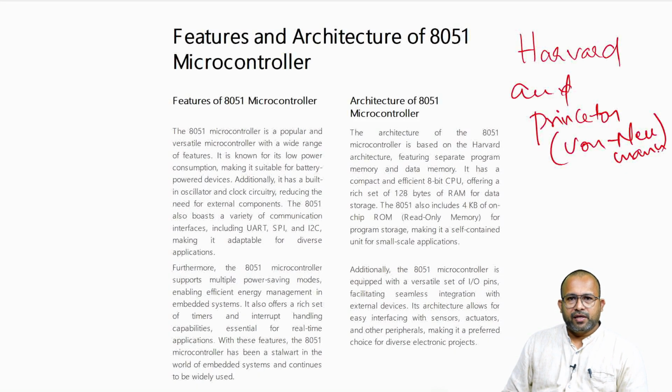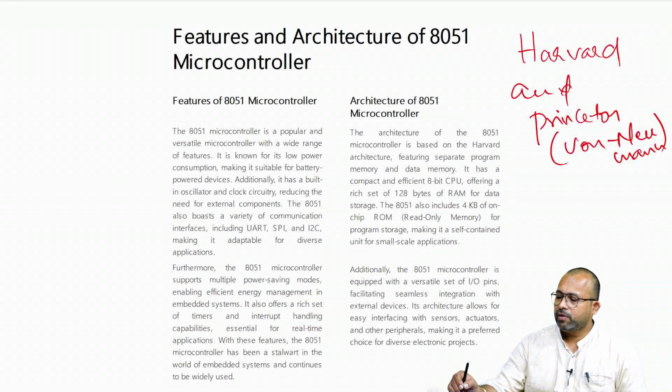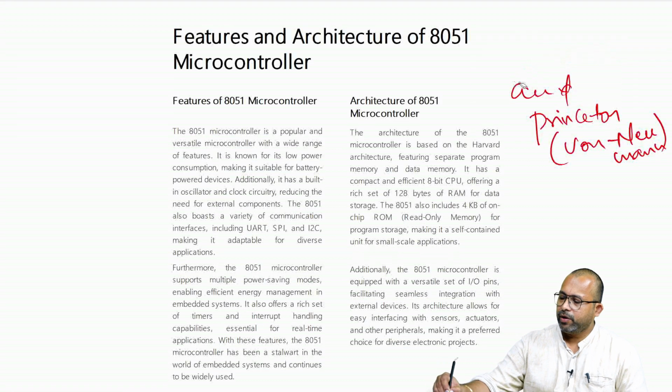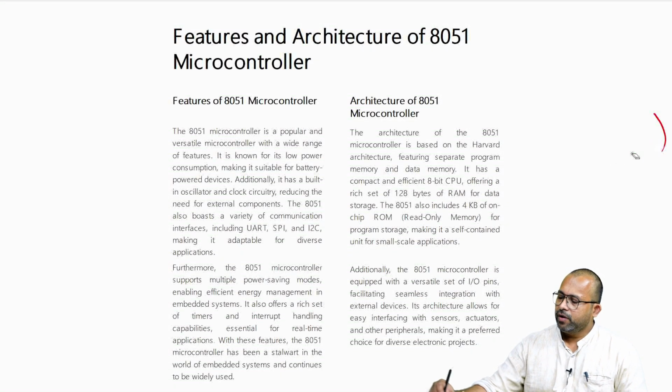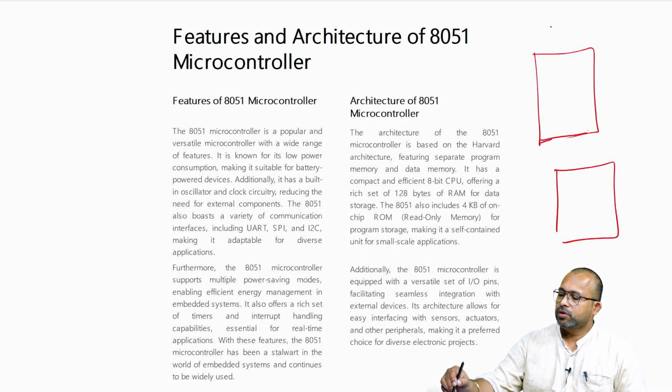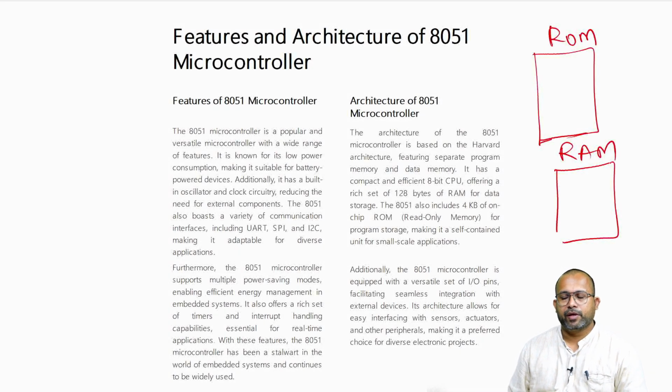Von Neumann was a scientist who worked at Princeton University, and the other architecture was developed at Harvard. The Harvard memory architecture is incorporated in this Intel 8051 microcontroller, which means there are separate address spaces for both ROM, the program memory, and RAM, the data memory.